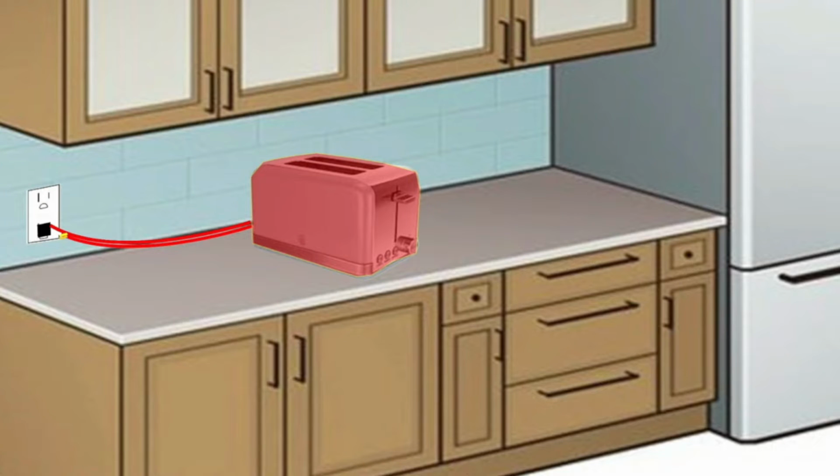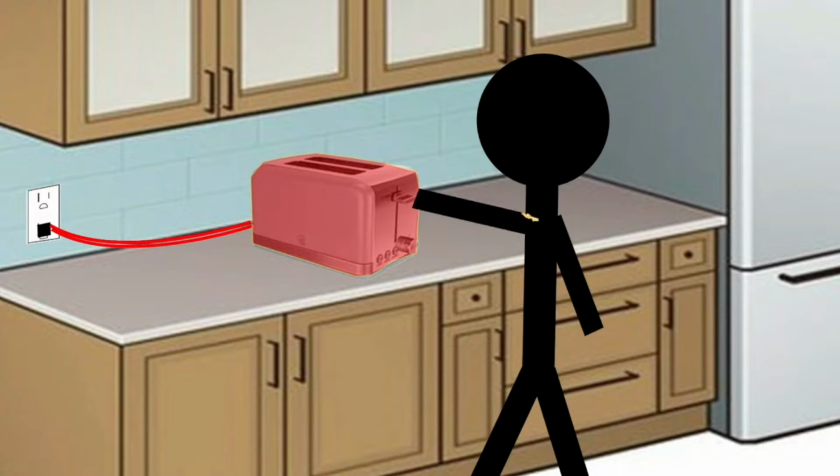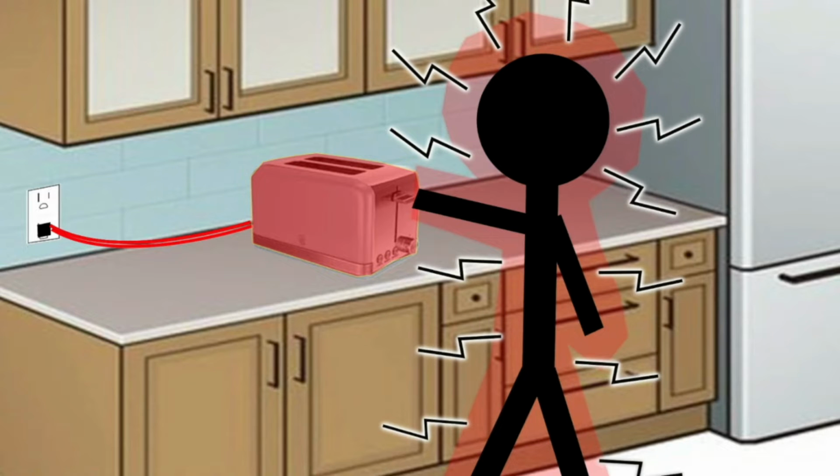Since we're probably most familiar with what a GFCI is, let's start with that and we'll go from there. So a GFCI is designed to prevent a ground fault. That's why it's called a ground fault circuit interrupter. A ground fault is where current goes through a path that is not intended. And this path could be a person. And the GFCI will trip and stop that current from flowing and protect that person from being electrocuted.